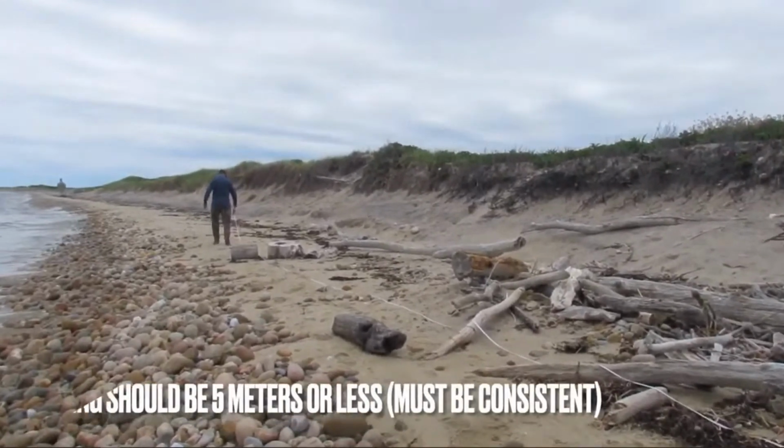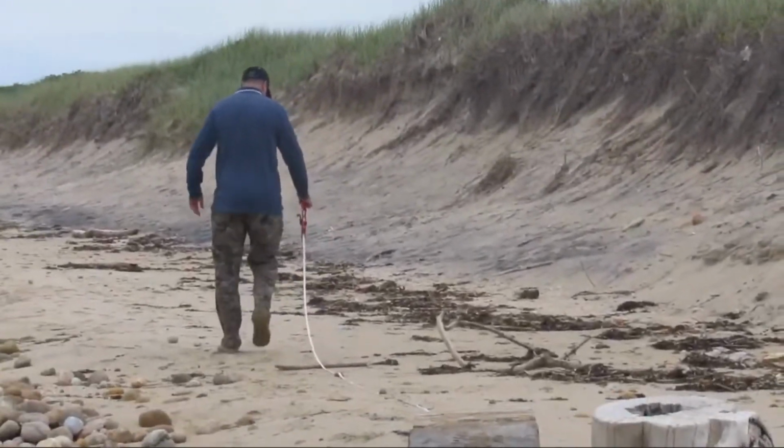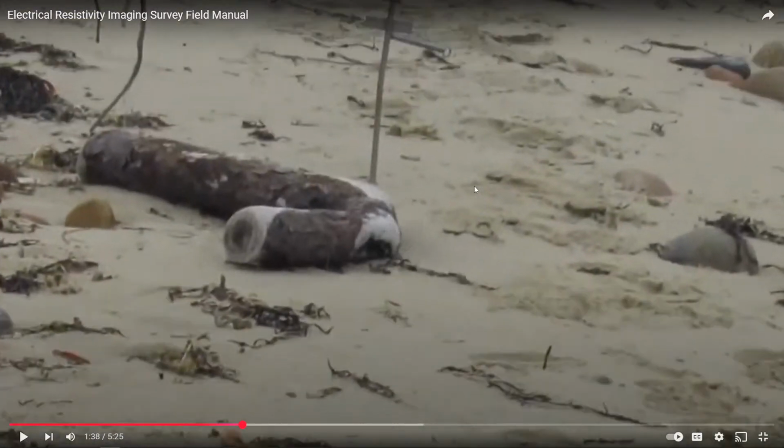Depending on your site, you must determine how far apart the electrode spacing should be. They are spaced at 5 meters directly on the cable, but you can do less depending on the length of your site. Once this is determined, the electrode should be placed at each interval. Remember, they said they place them at 5 meter intervals. That's because they want to go deep. And if you want to go deeper, you place them at a larger interval.